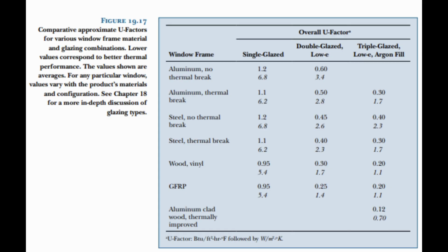The next section is glazing. Single glazing is accepted in the mildest climates because of its low resistance to heat flow and moisture condensation. Double glazing is the minimum that will meet the energy code requirements in most climate zones. And here's an example of that.